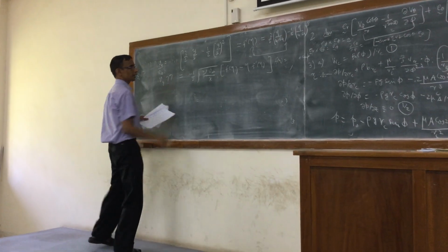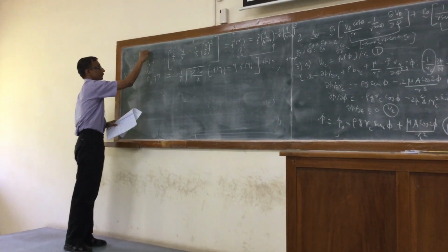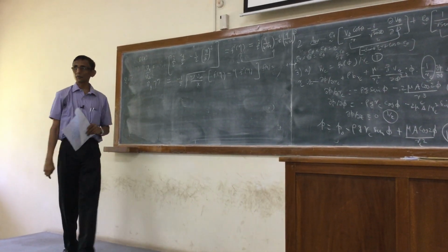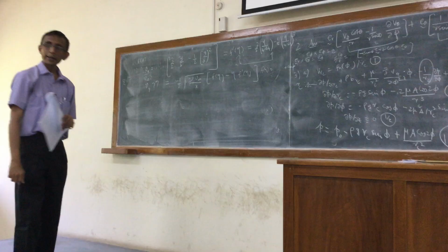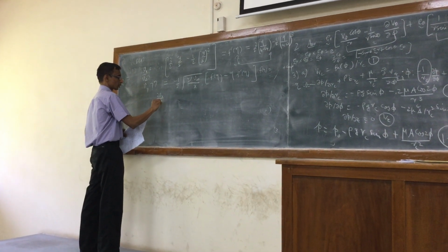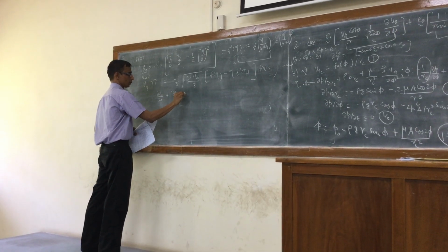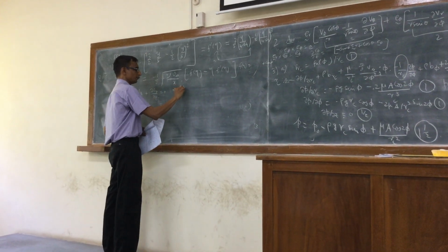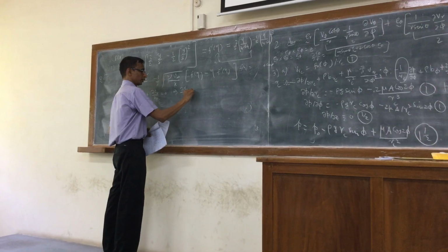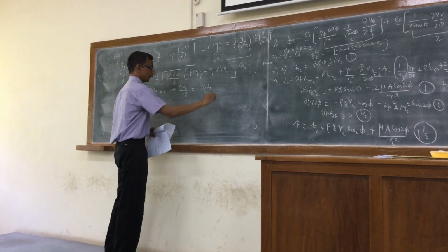Another method, without worrying about the eta now, because delta is of course a function of x. Another way is to get Vy directly from the continuity equation. So from this, clearly dVy by dy is minus dVx by dx.